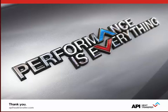All right, thanks, Sebastian. Another one in that same vein: can you comply with specifications like API 660 or ISO specs, for example? Yes, of course. Those are very common specifications. There are variations of them for shell and tube, plate and frame, hairpin, and various other types of heat exchangers. We've seen them all. We even go one step further and work with the customers and end users to identify parts of those specifications that they may not need, that may add cost.